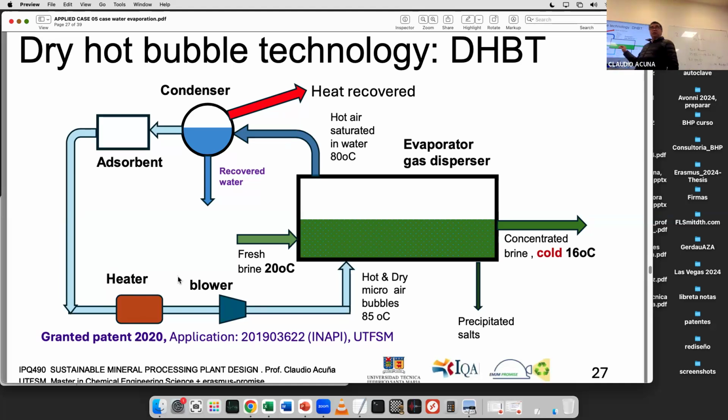Here's the money too. We need to have a gas disperser that does not have a lot of pressure drop. If you have a porous sparger, you need 60 psi. But if you have a very shallow one, I mean 1 meter, 1.5 meter height, and a very high concentration of saline water, the salinity will help you to have very tiny bubbles. So you can work with a very high porosity sparger, so you have less pressure drop. You follow the sequence, okay? Since you have surfactant solution, you don't need to have a small pore size. You can have a low pressure drop sparger. You know what I mean?